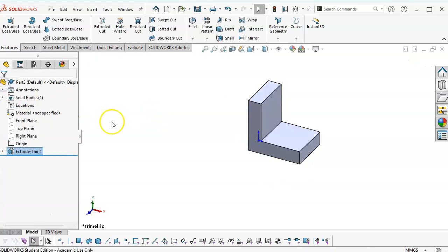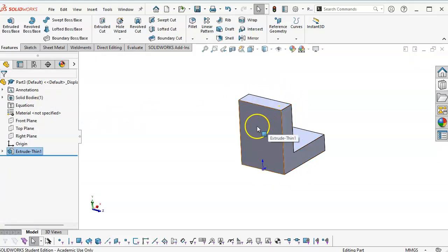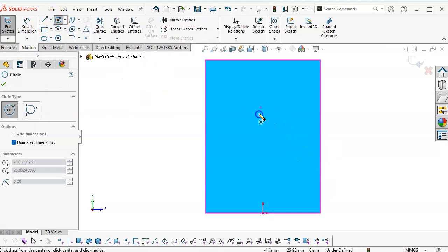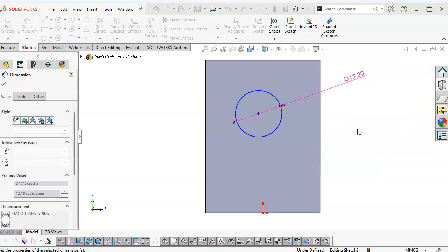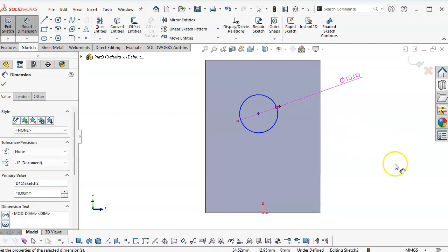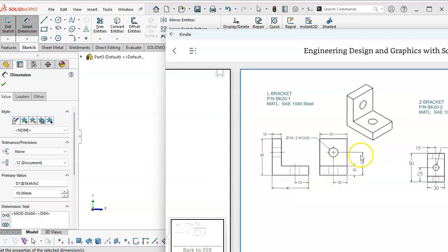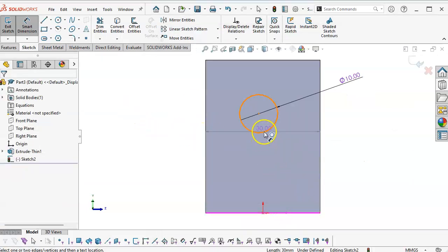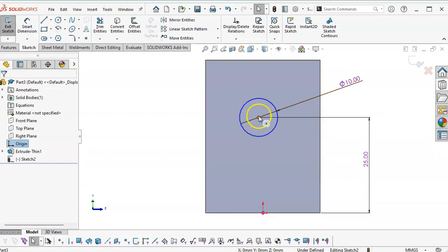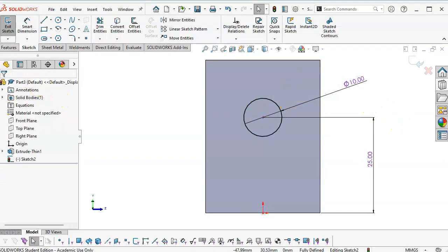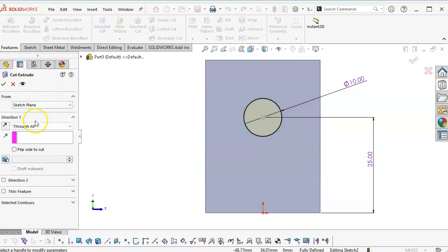All right, and for this one, we're going to go with the sketch geometry. We'll open up for a piece. I ignored the numeric input right after I did that, so 10 millimeter. This is going to be 15 millimeters off of that. Nope, it gives it as 25. The rest of them, nope, I guess it does give them at 25. So we'll go with the 25. And because these are going to stay centered, I'm going to select the origin, Control select the center point, and make it vertical. And then this is going to be an extrude cut up to next.